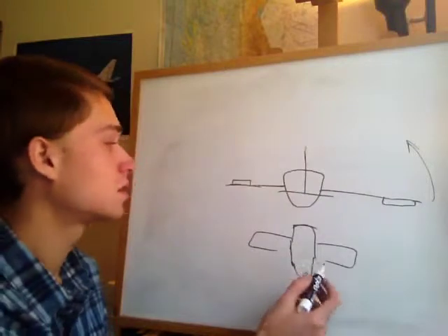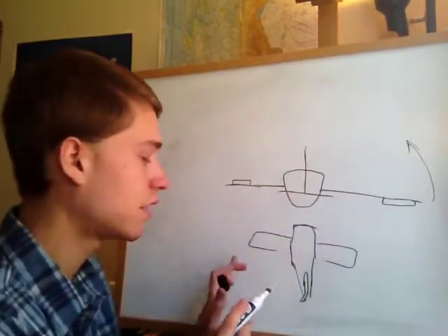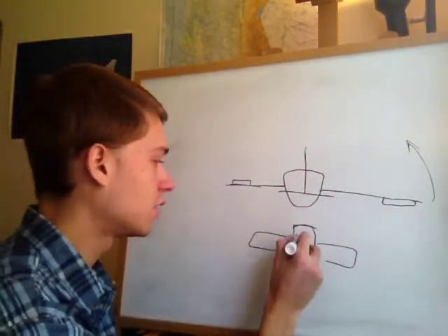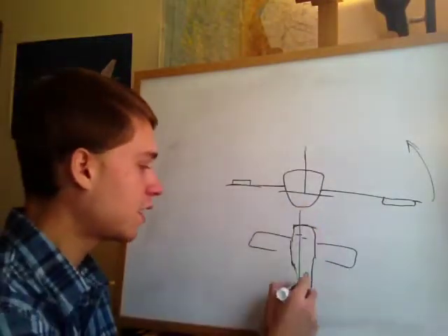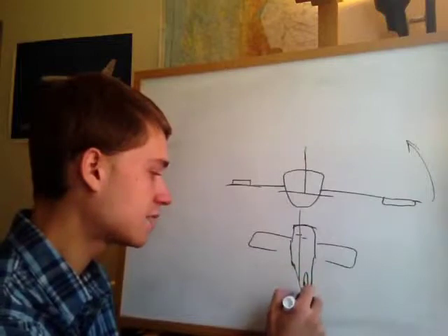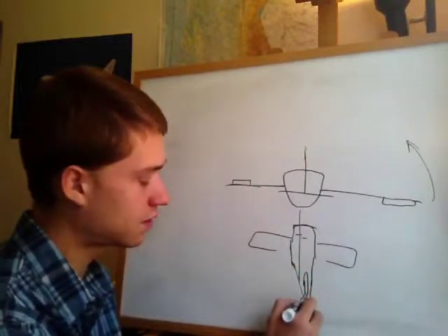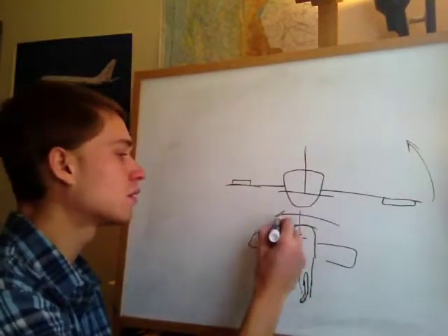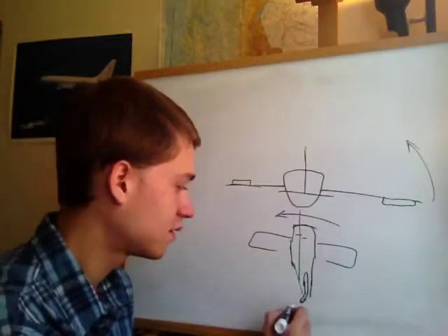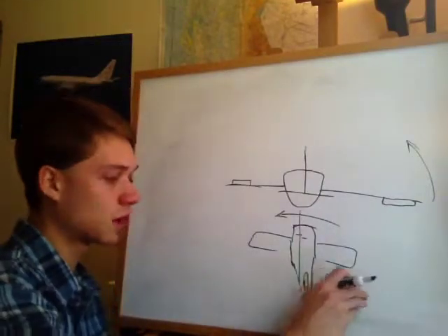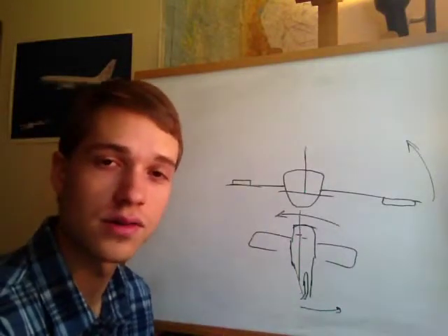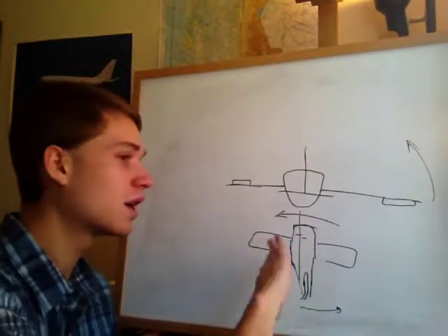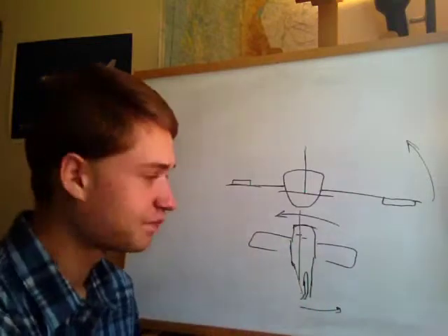And so we want to turn left, so we're going to push on the left rudder pedal. So here's a representation of that. We're pushing on the left rudder pedal, and the air is going to be hitting against that deflected surface, and that's going to turn the airplane nose to the left. It'll make the tail swing that way, and so the nose will come to the left, and that's how we coordinate our turns. That way, we're going to have the airplane turning as well as banking.